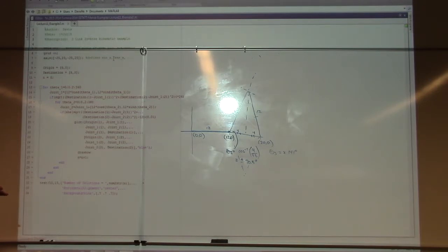Now, one thing to note on stepper motors is even though they're typically set up with a resolution of 1.8 degrees per step, you can have a reducing gear on them or belt to change that resolution.